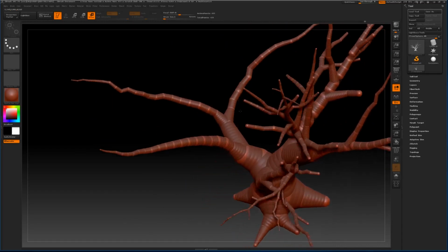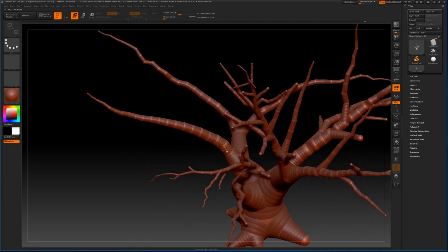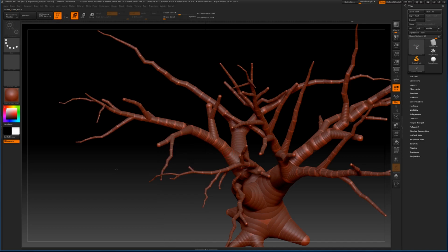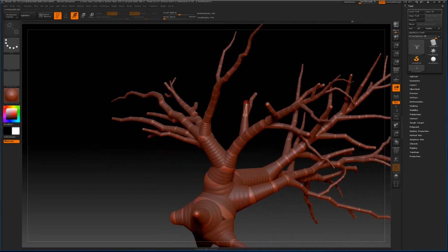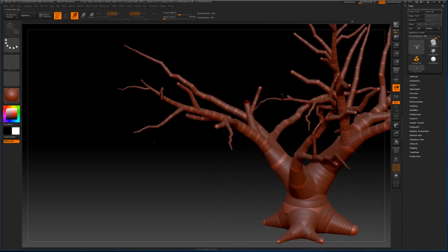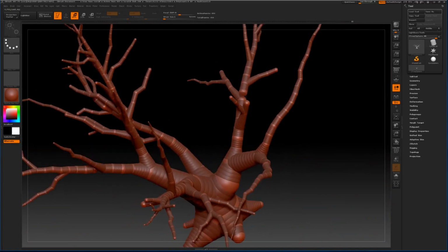And so we can just start adding our branches off this. So I will click move, select the first Z-sphere in this chain, go to Z plugin, branches start here, grow branches. That's pretty cool. Select this Z-sphere because it just kind of stops there. We could actually leave that. I'll leave that, and I'll go back and I'll show you how to delete branches as well.